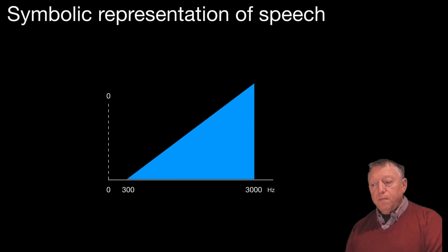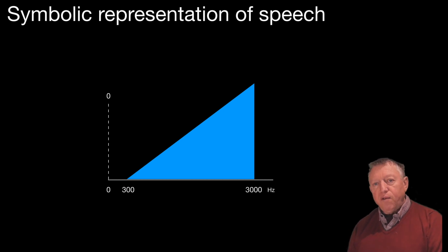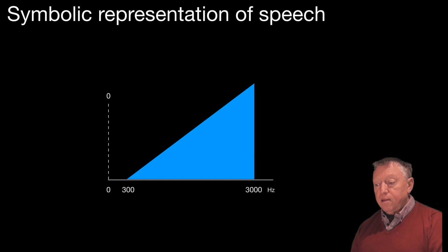And if we look at them, some people leave a small gap between the center frequency, perhaps the carrier frequency or the IF frequency, and the beginning of the waveform at 300 Hertz, because, as you recall, voice for amateurs anyway is between 300 and 3000 Hertz.